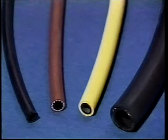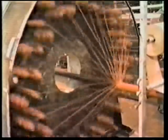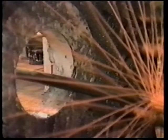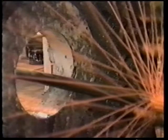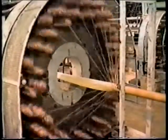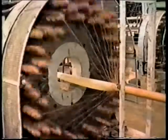This construction is common for air and general service hose. The horizontal braided hoses are constructed on a rigid mandrel, which is generally a steel pole. A seamless rubber tube is constructed on the mandrel, which supports the tube during manufacture. The mandrel supports either wire or textile reinforcement to be applied at high tensions. This permits construction of a hose with close tolerances on the ID and high working pressure ratings.